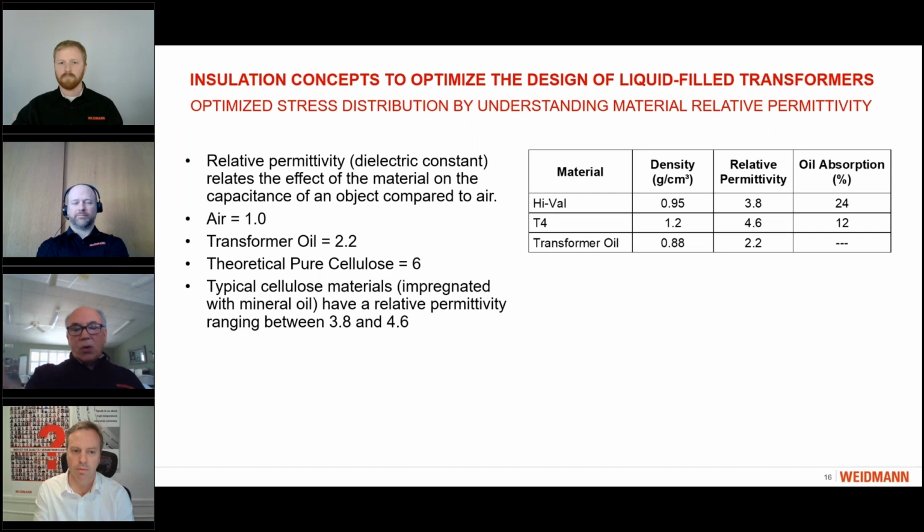So whoever had the question probably knew that, but in that case, ideally you would have the same relative permittivity between the liquid and the solid. So certainly 3.1 is much better than 2.2. In that case, we're able to put more of the stress on the solid insulation because we have a higher relative permittivity liquid. And when we share this presentation, there are some references. There was a paper that I wrote, and it's in the references, that talks about that.